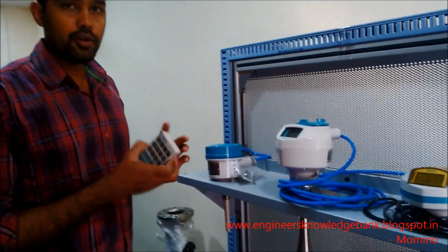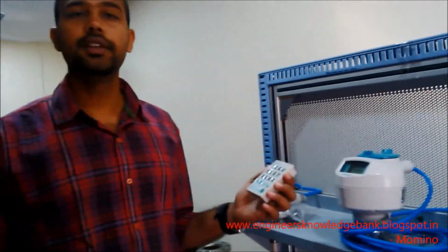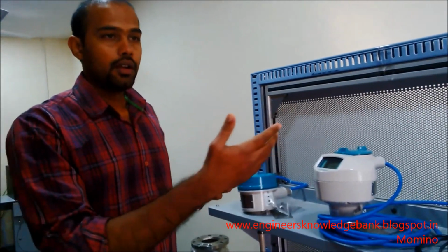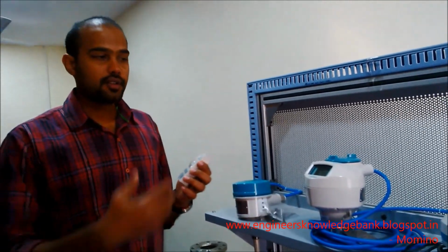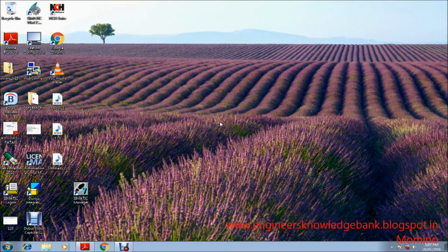If you want to do manual parameterization, you can use a handheld remote for this LR250. You can change it from the remote location itself, and you can parameterize it according to your need. So today's video shows how to communicate your process instruments with your Profibus PA protocol and your PC.